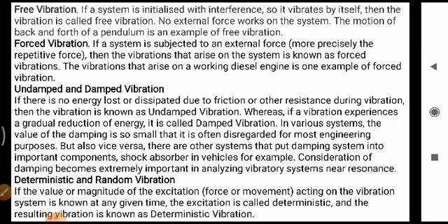In the next classification, we will be dealing with forced vibration. Free vibration we have discussed here, and a simple pendulum is a very good example of free vibration. Not the pendulum of a clock, it's a simple pendulum, because the pendulum of a clock will not stop its vibration. If any body is given an excitation and no resistance is offered to the body, it will continue its vibration. Otherwise, it will stop. Normally, we give oscillation to a simple pendulum in normal atmospheric conditions. Air is there, so air will offer resistance to the motion.